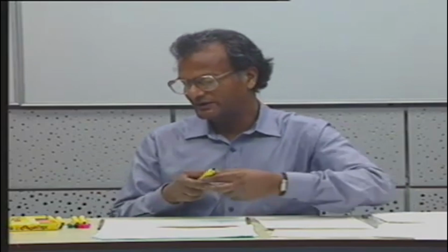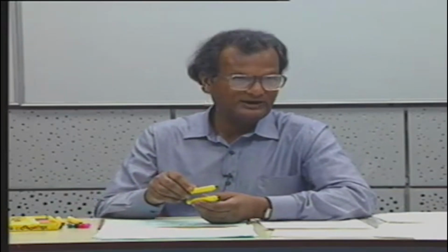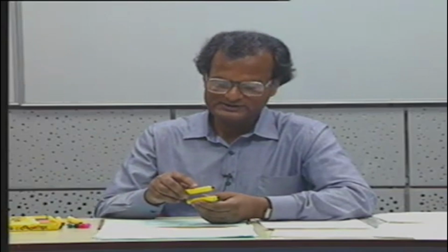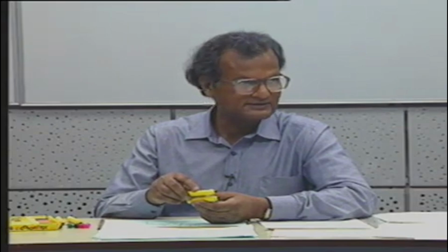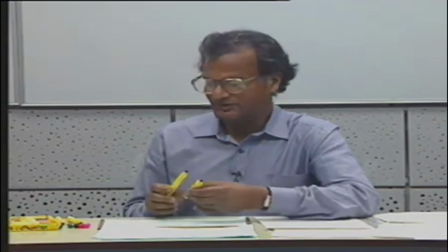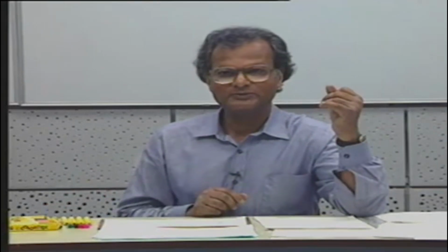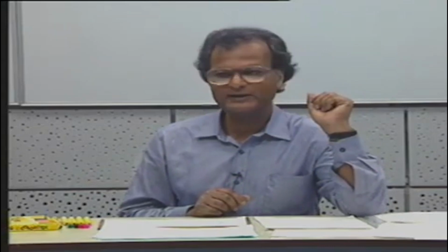For example, you can measure mechanical displacement. What you do is you put a parallel plate capacitor, and if this is displaced, if this is loaded, then the distance decreases, so the capacitance increases, and that capacitance could be measured by the help of this circuit. Wien bridge is a very popular circuit for instrumentation. Next time, that means tomorrow, we will consider negative feedback and its effects.